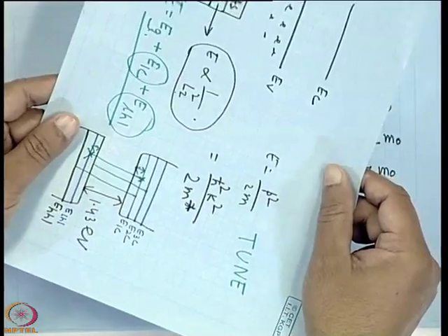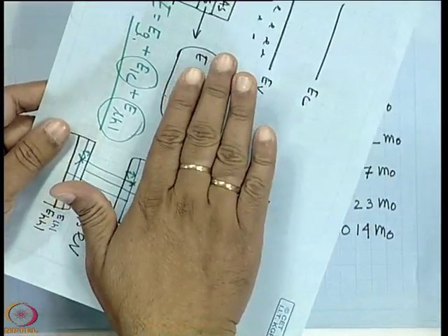So, those are the advantages of silicon, and how you can fabricate gallium arsenide on silicon, because normally gallium arsenide is made on gallium arsenide. Suppose this is a gallium arsenide wafer. So, you have to use a gallium arsenide wafer for the fabrication of gallium arsenide layers or p-n junction or MOS device, whatever device you would like to make on gallium arsenide.